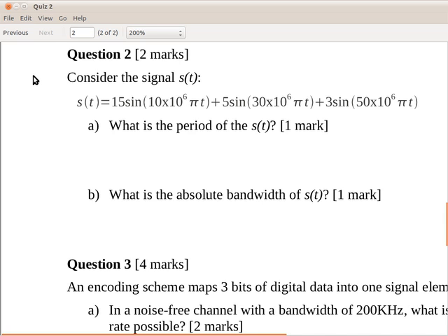In the previous question, that wasn't true. Remember, we had 30, 60 and 100 hertz. They were not all multiples of one of the components. If this was 90, it would be, but it was in fact 100. So it's 3.33 times. We're not multiples of one of the component frequencies. That's the definition of the fundamental frequency: multiples of one of the component frequencies.